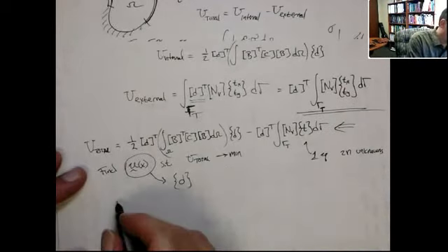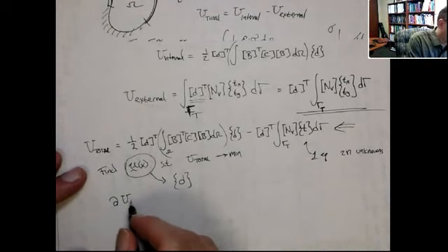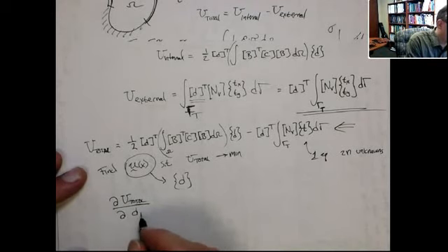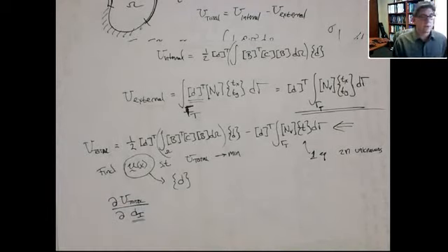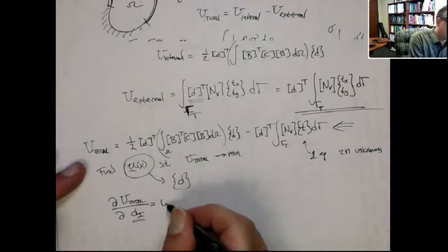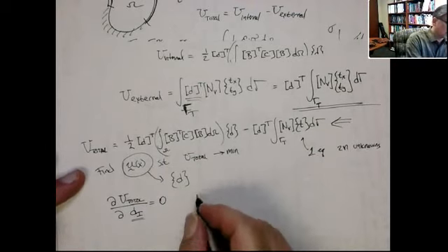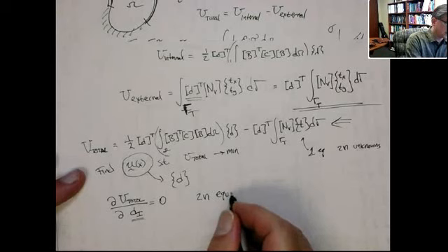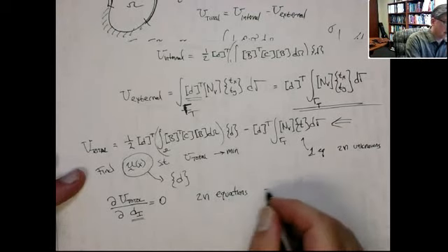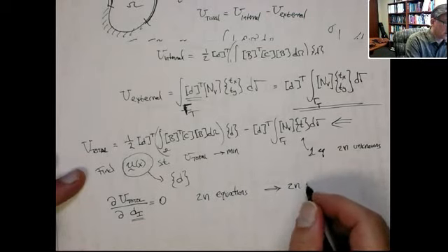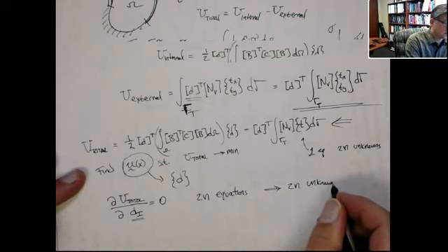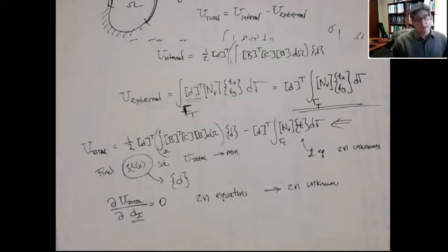But if we look at taking the derivative of U total with respect to di, where i is one of those degrees of freedom, and set that equal to 0, that's finding the extremal point. This is now going to give me 2n equations that I can solve for the 2n unknowns. Okay? So that's how we're minimizing. We're just looking for the stationary point or the extremal point, right? So it's just that simple.